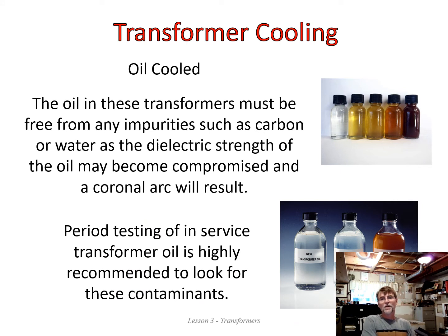Now, the oil in these transformers has to be very carefully monitored because it must be dielectric. Because the coil is submerged in this oil, we don't want that oil to be conductive. When you're doing regular maintenance of your transformer substation, and I was involved in this for years, typically once a year the substation would be shut down, and we would go in and clean every surface. All the dust has to go, because dust is probably conductive, depending on its makeup, and if you put dust on the wires at the insulators, it reduces the insulation value of the insulator, so all the dust has to be removed.